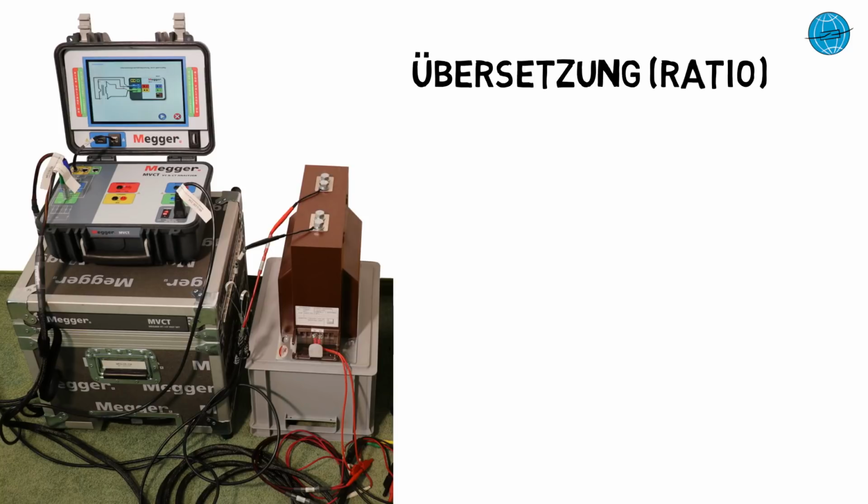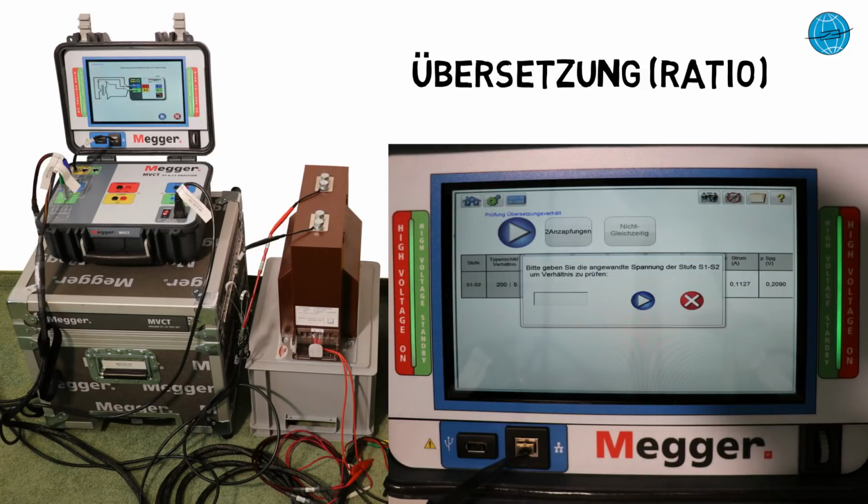Now let's take a look at the measurement of the ratio and start this time with MEGGER's MVCT. We do the ratio measurement on our already known current transformer. The test setup is identical and we start the test. The MVCT now wants to know via dialog box with which voltage should be tested. Here the user has to think along and enter a value. Since we have previously determined the knee point voltage at greater than 11 volts, we decide for 10 volts, a test voltage that is slightly below the knee point.